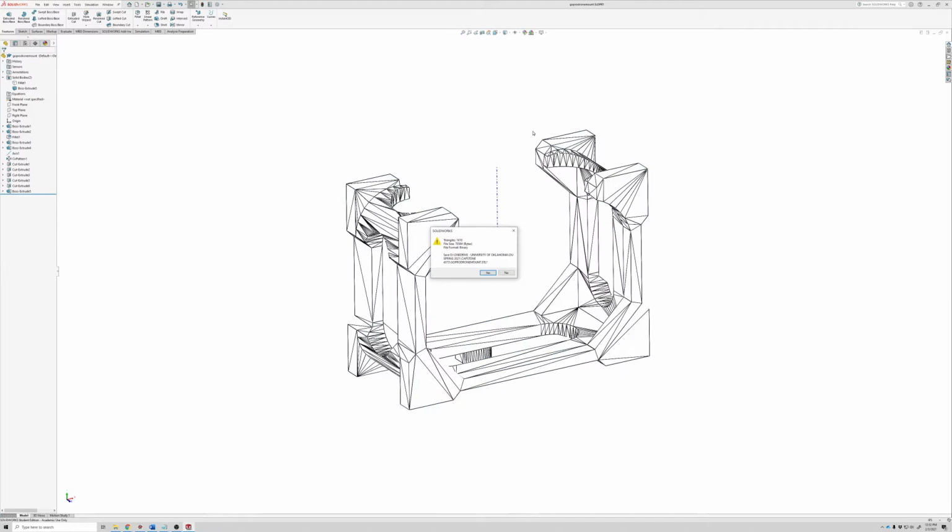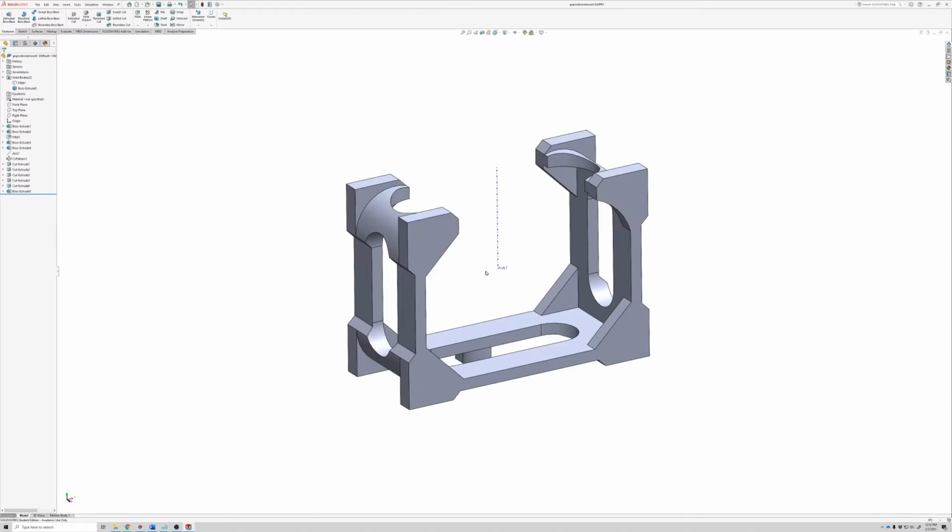In fact, it's cool in SOLIDWORKS. It actually shows you the 3D representation here temporarily. Noticing again, as in SOLIDWORKS style, you get a few missing edges and things, but in my experience, they still show up whenever you get into the slicer program. You'll be able to tell otherwise. Triangles, 1,410. Those are basically the surface triangles that define the object. File size, very, very small, 70 kilobytes, binary format. All I have to do is click yes. Sounds good? Okay, it's saved. So that's the first step.